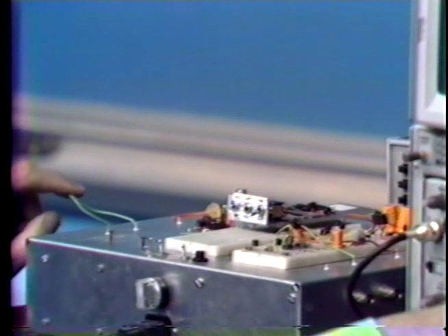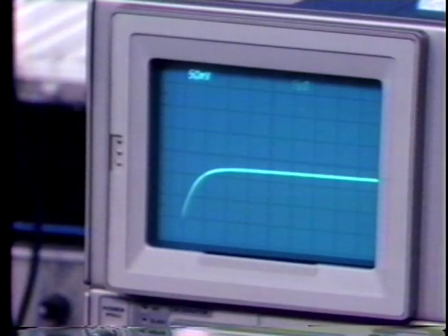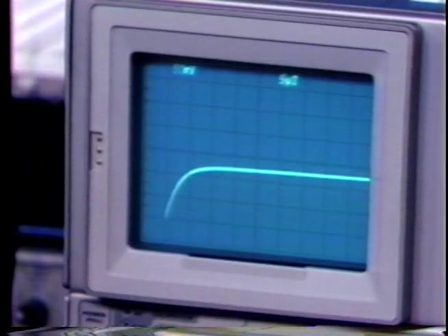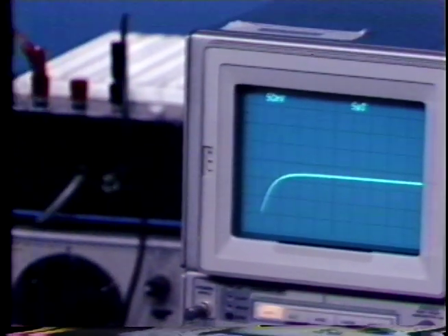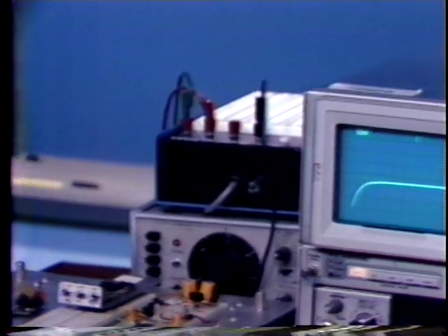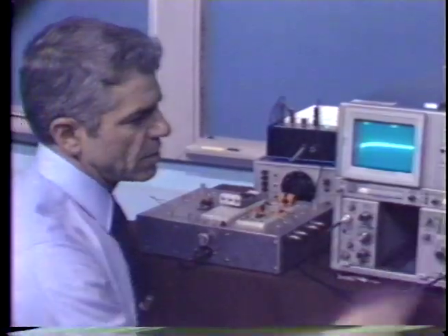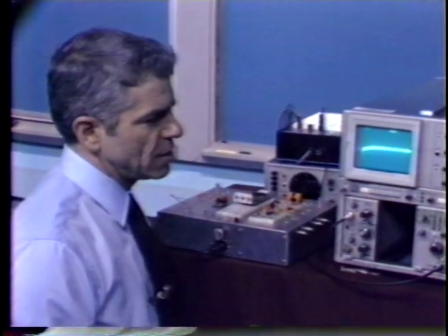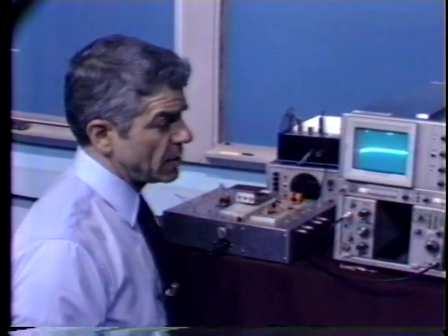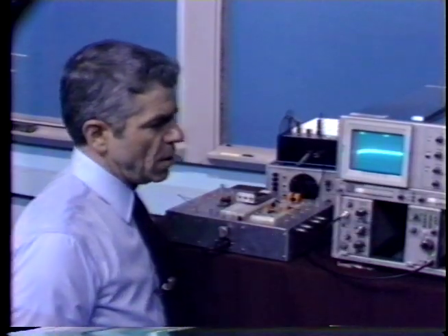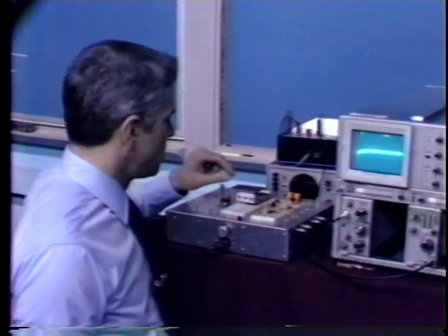Well, what we find is, again, a delayed settling time. This sort of compensation gives us a pole zero doublet if we look at it. We get to about 90% of final value very quickly on the leading edge, but it takes much, much longer. The response is basically two exponentials, one of which has a much longer time constant than the other, and we see the quite prolonged settling to final value.